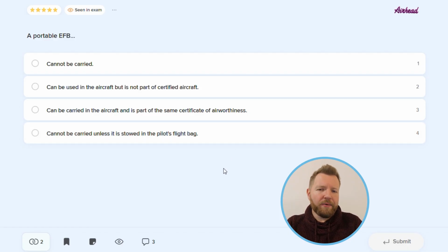Okay, electronic flight bags we can divide into 2 types in terms of software and 2 classes when it comes to the hardware. First, let's look into the difference between Type Alpha and Type Bravo software. Type Alpha are applications whose misuse or malfunction has no adverse effect on flight safety. Type Bravo, on the other hand, are applications for which evaluation of the hazards presented by misuse or malfunction is required. Good example here can be any performance calculation software.